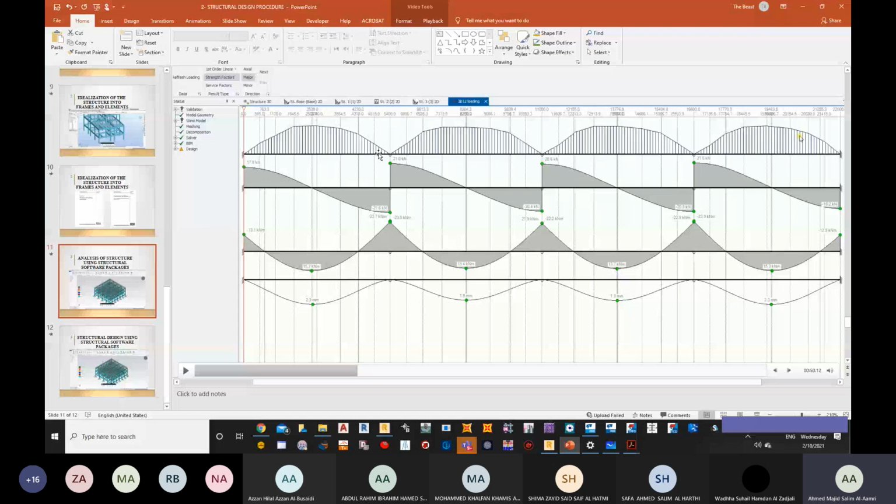So if you want to design manually, then you can take these values from the analysis and design them directly. So I have M to be 13.1, and then directly I'll be using that equation of As to calculate how much reinforcement is required. Okay.